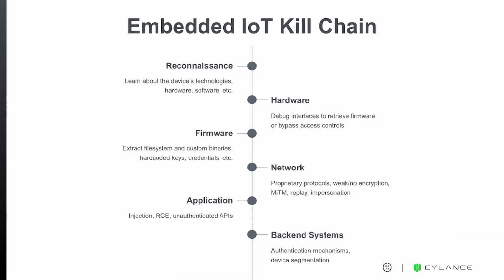Or traditional buffer overflows through the use of insecure functions from the standard C library. A lot of what we find is that basic exploit mitigations are not enabled on these devices or not present. So, where stack-based buffer overflows have not been seen quite often at all in traditional enterprise computing, right? They're back again, once again, in embedded systems and fairly common, due to the lack of just basic defenses like DEP or ASLR.